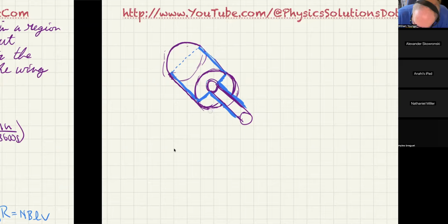And now that's basically the electric generator. So if you had some mechanical way of rotating this object, which we clearly have, again, these parts have to be dashed because we're not actually seeing through the thing. But that's how the wire goes. And we use what's called slip rings, and slip rings allow current to flow from a wire, let's say, that connects to this wire. And then there's another wire that connects to this wire.